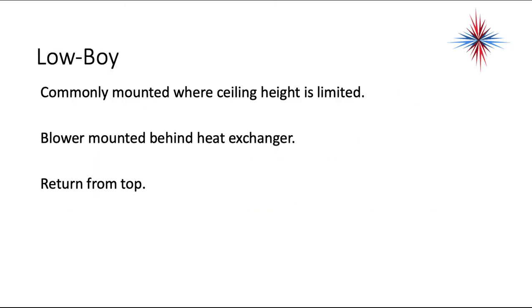Another type of furnace is a lowboy furnace. Don't see these that often anymore because there's some other options like the horizontal furnaces now, but it's commonly mounted where ceiling height is limited. You see these sometimes in basements where the ceiling is very low and you don't have a lot of height. The blower is mounted behind the heat exchanger, and both the return and the supply are on the top.